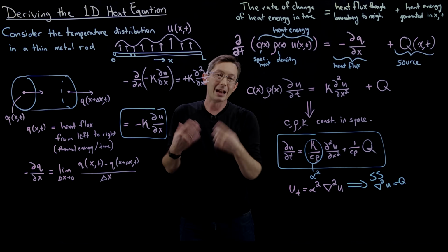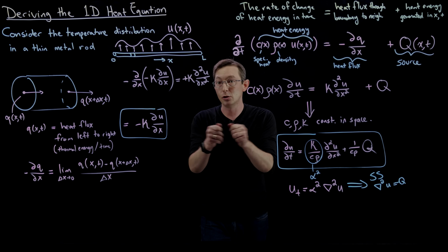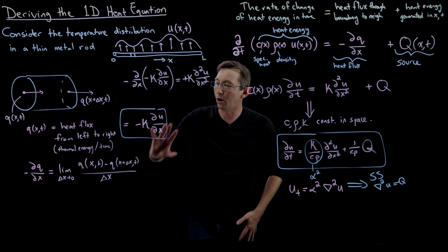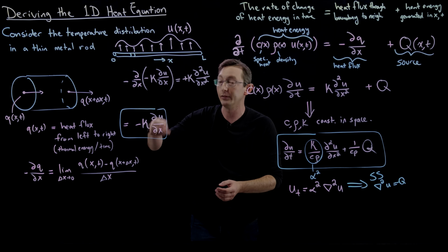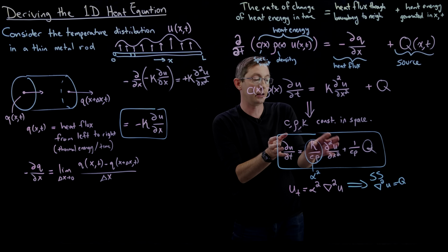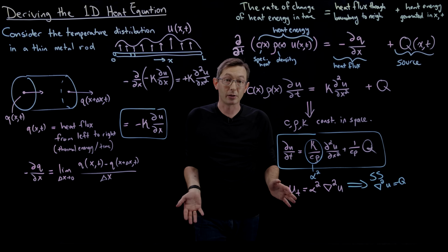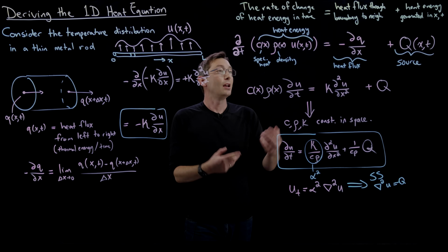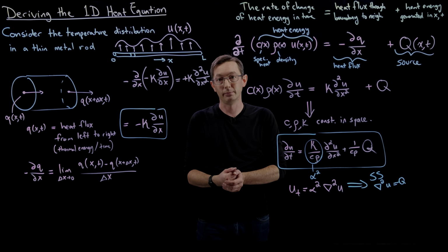And this common sense conservation of heat energy allows us to mathematically write down this partial differential equation. Now we had to use things we knew, like this conservation of thermal energy. We assumed that was true. We also used all of the experiments that Fourier conglomerated into his law of heat conduction so that we could get this diffusion term here. But the process is actually relatively straightforward. You take a conservation law and some know-how and some vector calculus, and you derive a partial differential equation.